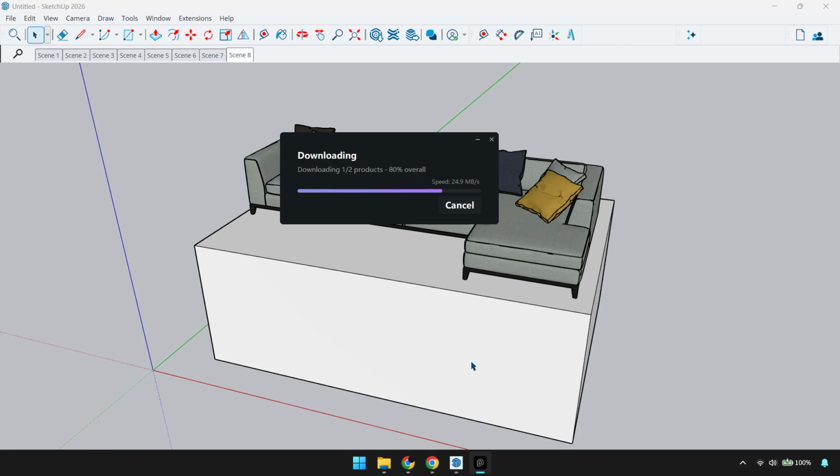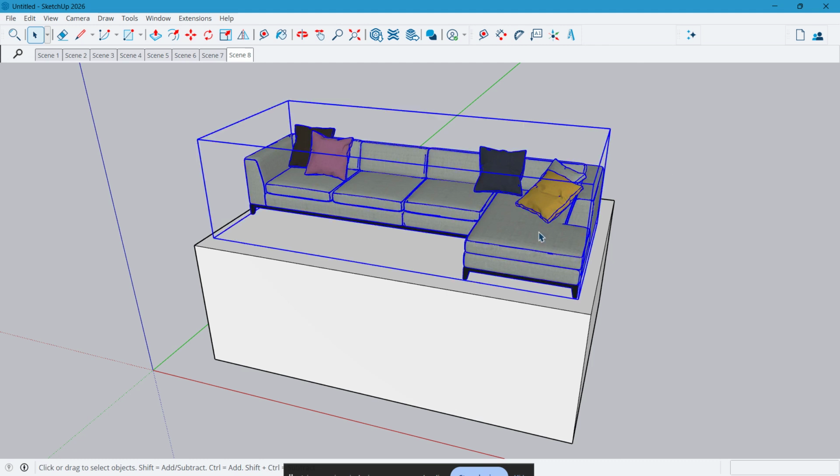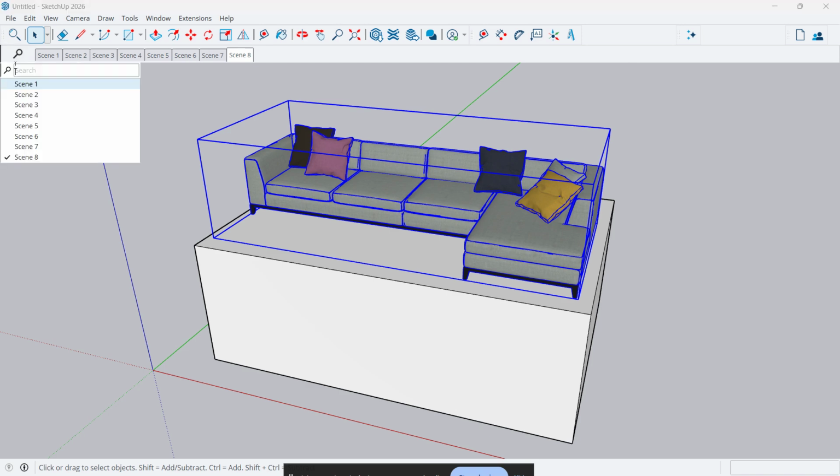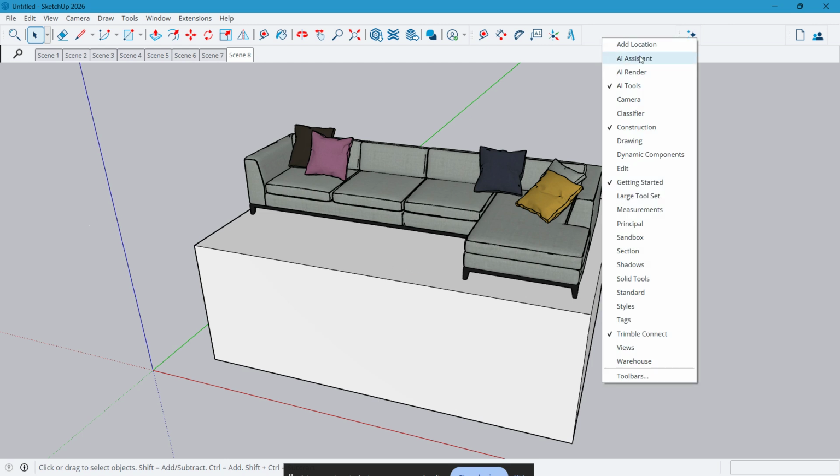You can also work with materials in a smart way. If you apply a material in SketchUp, D5 will recognize the material name during sync. Then, inside D5 Render, you can open the asset library and replace that basic SketchUp texture with a high-quality PBR material. That means you can keep your modeling workflow simple in SketchUp while upgrading the visual quality inside D5 with realistic surfaces, better reflections, and richer detail.